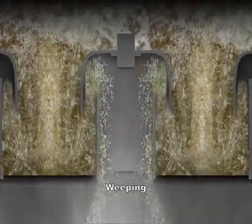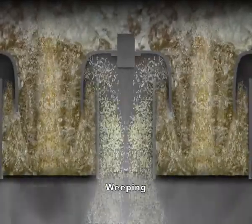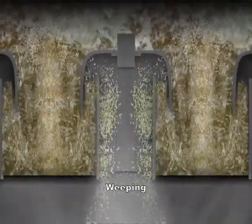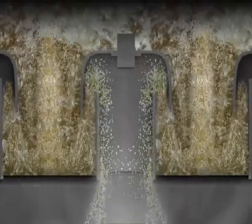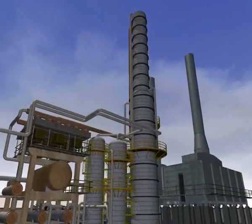Excessive weeping can result in dumping, in which all liquid will move down to the base of the column. The steady state will be compromised, and it may be necessary to restart the process. Weeping can be detected by a sharp pressure drop in the column in combination with reduced efficiency.